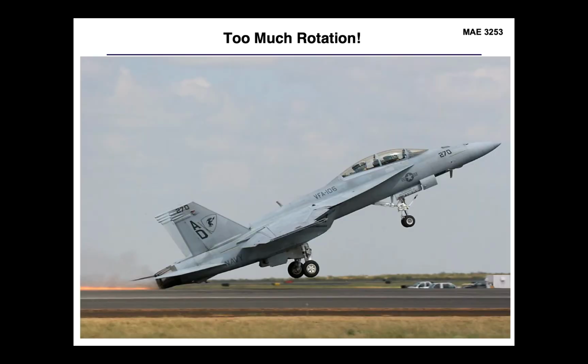And of course, it is possible to have too much rotation as well. So notice the distance between the main landing gear and the aft section of your aircraft. If you rotate too quickly, then you can obviously hit your tail and do a lot of damage to your aircraft.